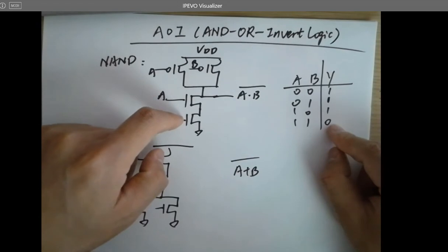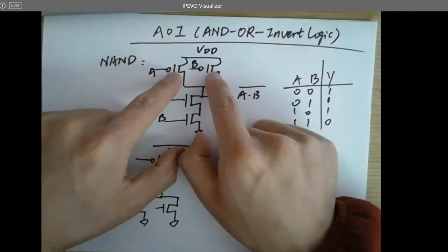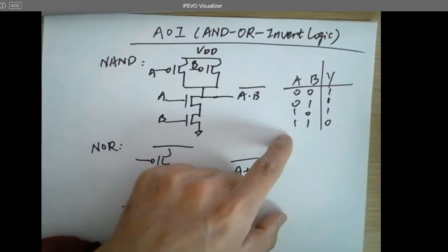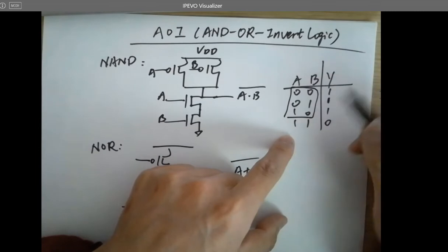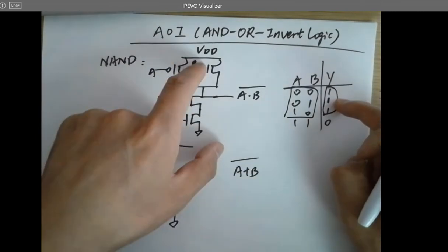All right. And for the AND logic underneath the bar, the PMOSes have to be in parallel, because if you look at the logic here, whenever it's being pulled up to VDD, which means you have to use the PMOSes to pull it up to VDD.